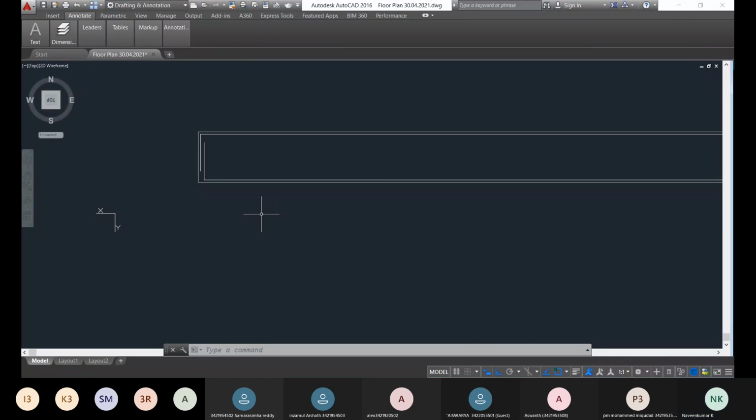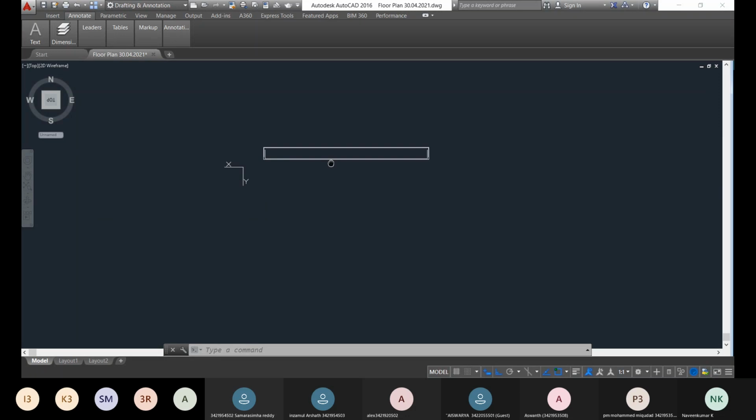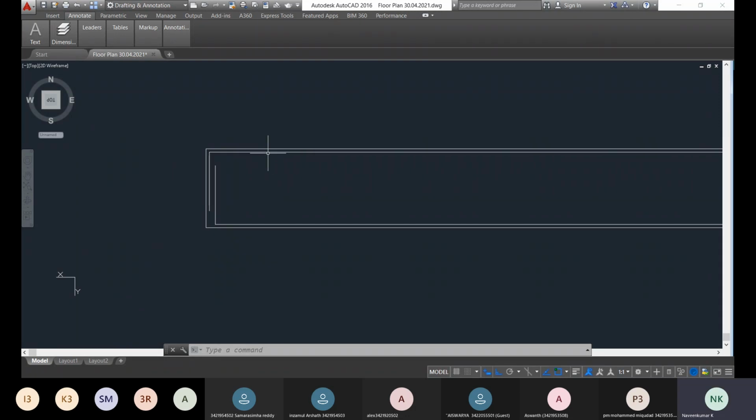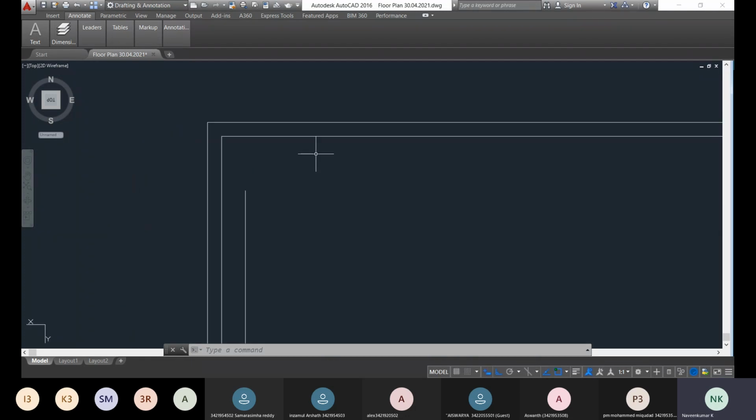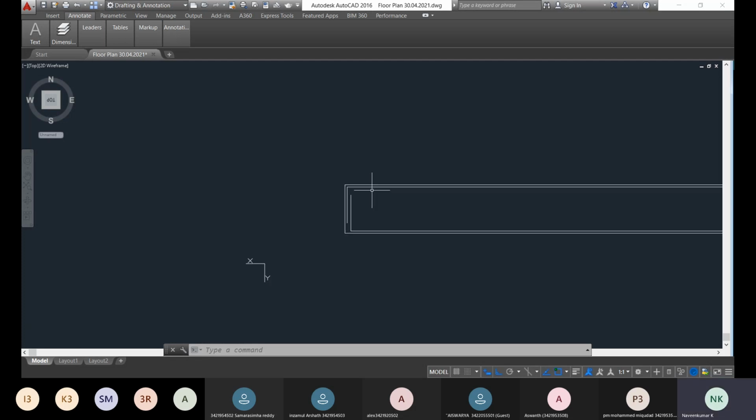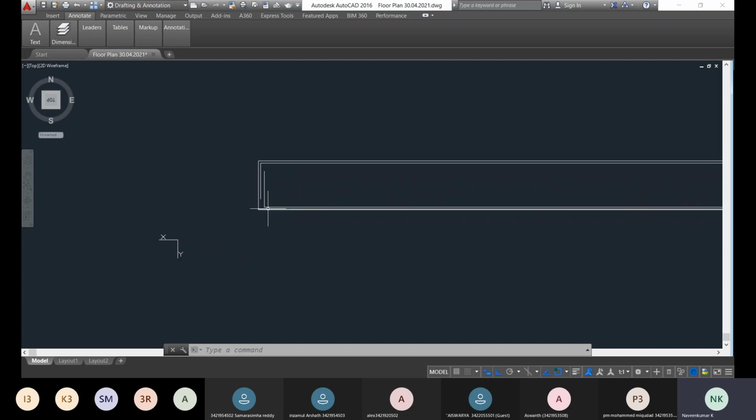So therefore, the distribution reinforcement will take care of the shear force. Therefore, the spacing between the distribution bars at the corners will be less, and the spacing at the midspan will be more. Okay, so that is the thing. So now we're going to see the distribution bar along the longitudinal direction. You can see it as dots only.